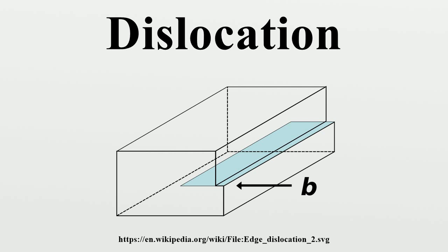One additional difference between dislocation slip and climb is the temperature dependence. Climb occurs much more rapidly at high temperatures than low temperatures due to an increase in vacancy motion. Slip, on the other hand, has only a small dependence on temperature.